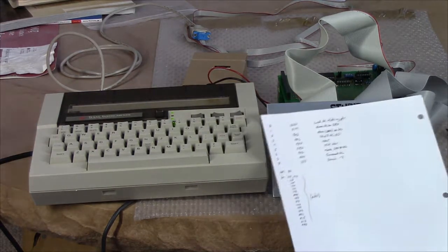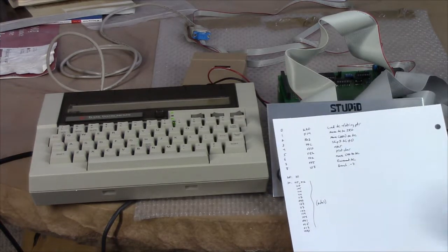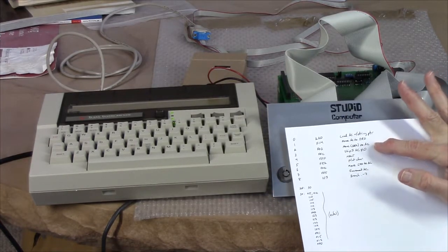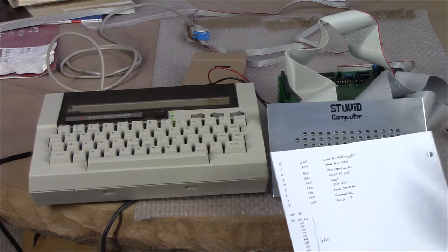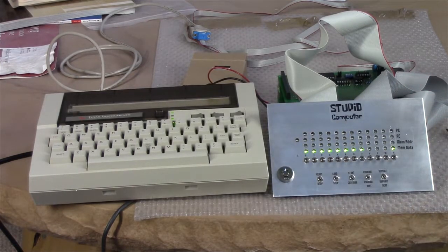So I've worked around that in this code. I am using the indirect register to load the string, but I'm incrementing it sort of manually by actually moving that indirect register value to the accumulator, incrementing it, and then moving it back, which is really horrible.